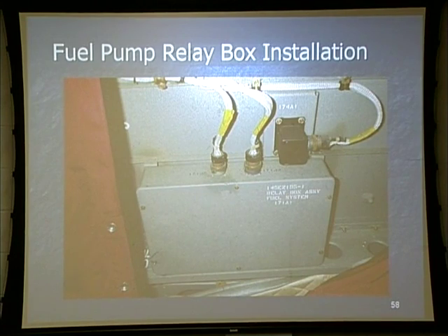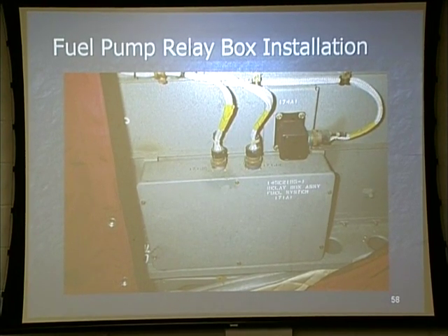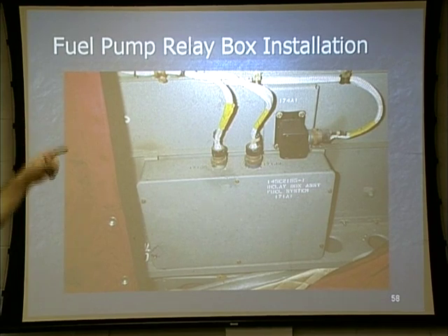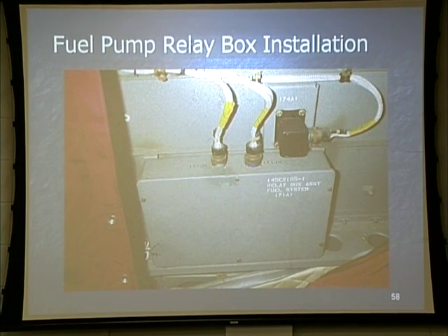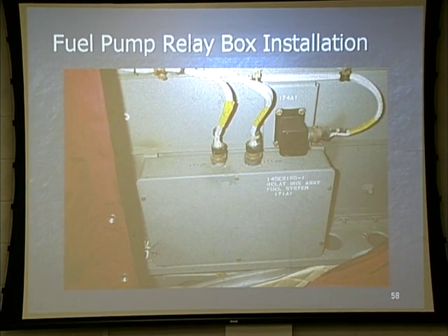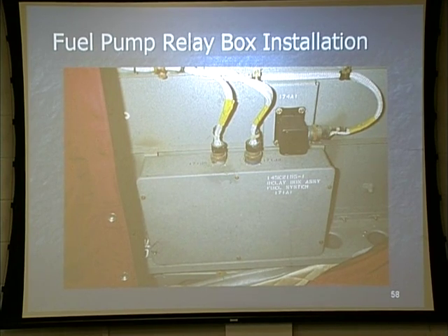Now, this fuel pump relay box is behind the soundproofing. We're just showing it to you because reality is this is where the signals go to. And then it goes up to the cockpit. Everybody's kind of sometimes under the impression that it goes straight to the cockpit, so they don't understand how it dictates or determines the average fuel before it goes up to the gauge. It all goes to a relay box which does all that. Okay? And also provides for all the electricity.